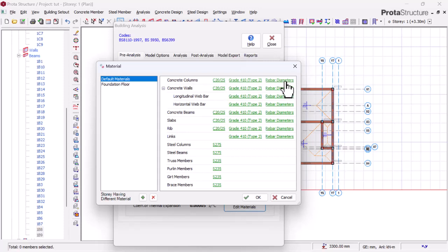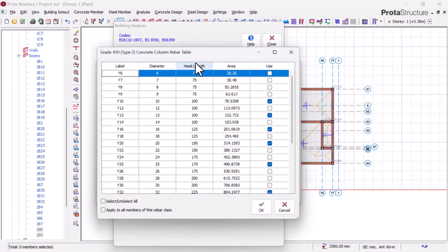So doing this, you go to the column, the concrete column. What do we do here? You highlight the bubble for the column. Now, look at the size of the bar. These are the labels telling you various sizes of the bar, the Y16 and all of them. These are all sizes: the 16 mm, the 7 mm, the 10 mm, the 12, the 20, and so forth. This other one is the diameter, still referencing the same thing. Where you have the Y13 is still 13, and this is your hook length and the area of the reinforcement.